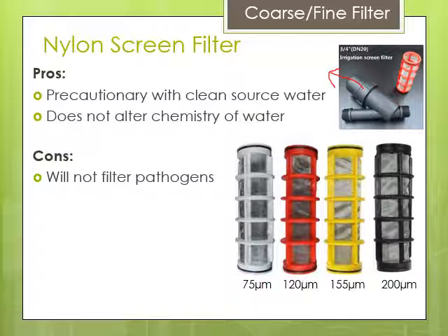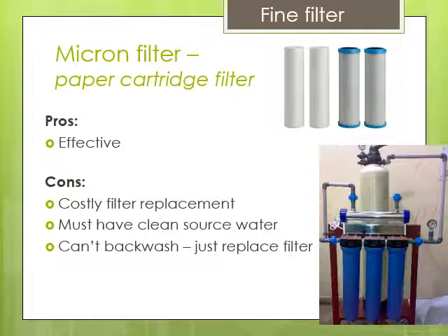A lot of the time in greenhouses, these small filters are just an added insurance step. For example, say your main filtration is in the barn and water's going out to the greenhouse to maybe your irrigation boom. Typically they'll throw a couple of screen filters on the actual irrigation boom, because you don't want that machine to get plugged since it's hard to work on and it's critical. So it's easier to just clean a little screen filter periodically to make sure your boom is operating properly, rather than having to pull nozzles and put new nozzles on, which is a real pain in the butt.